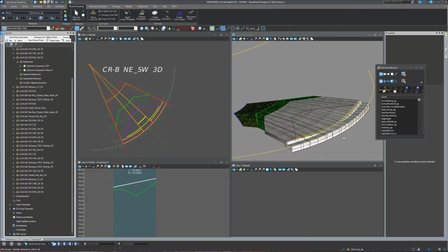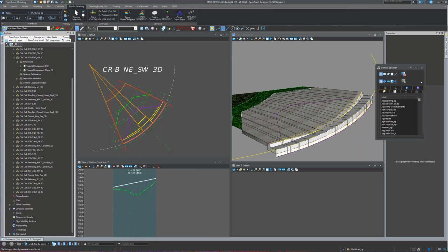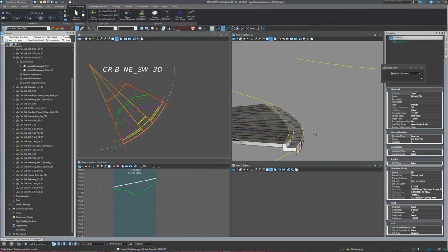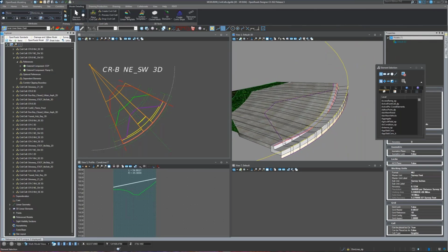All right. So you can see that we've got the sidewalk here. We've got 6-inch concrete sidewalk because this is a curb ramp and a return. So that's going to be 6-inch concrete sidewalk. That's important. We've got our curb coming through here, and you can see that the curb drops down to drop curb in here. In order to do that, we've got to drop the curb face down, but we've also got to push this curb face out to meet up with the gutter right here.